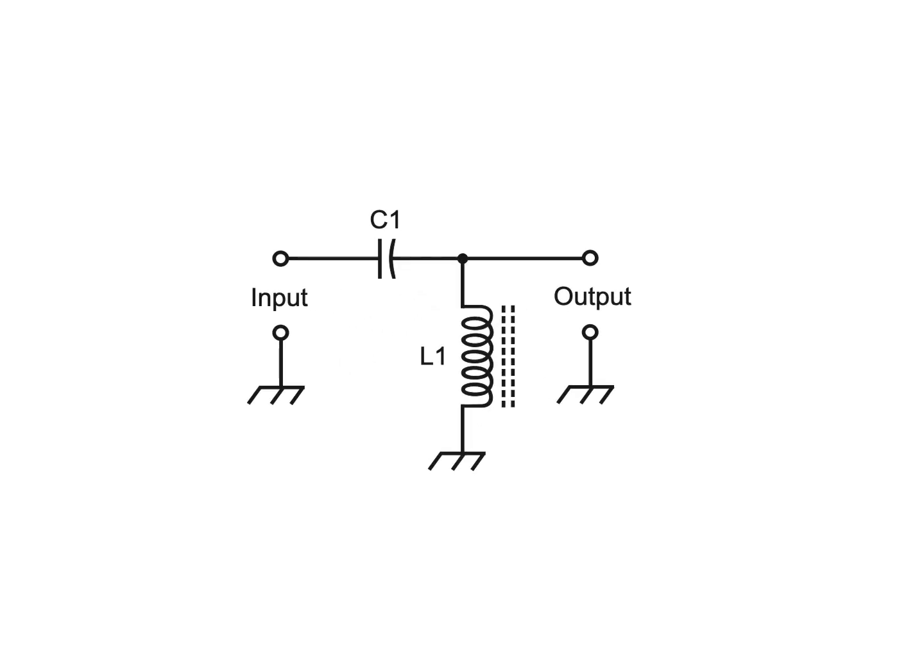This shows a simple inductance capacitance, LC, circuit. Note its resemblance to the L network before. In this case, the inductor and capacitor have been reversed from their relative positions in the earlier case. In addition, this circuit has a different purpose than the other one does. The previous circuit works mainly for the purpose of tuning an antenna system, or matching the output of a transmitter to the characteristics of a particular antenna. The circuit here is designed to let signals pass through, or not, depending on their frequency.